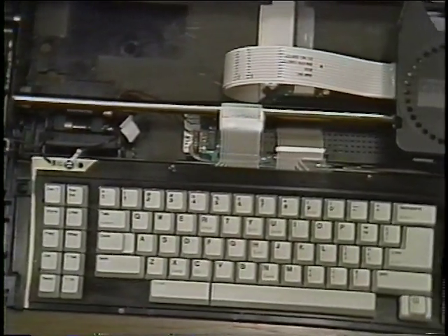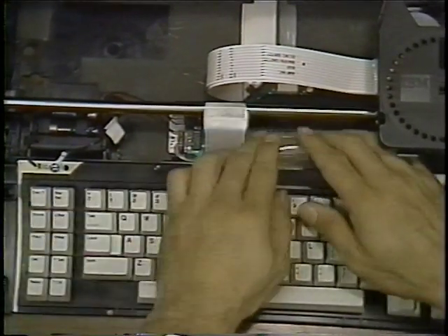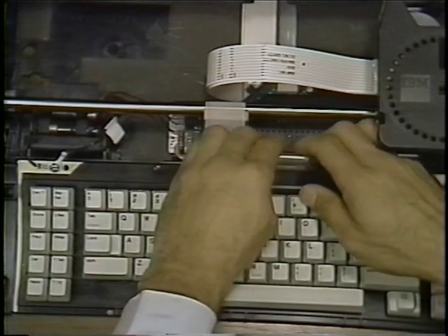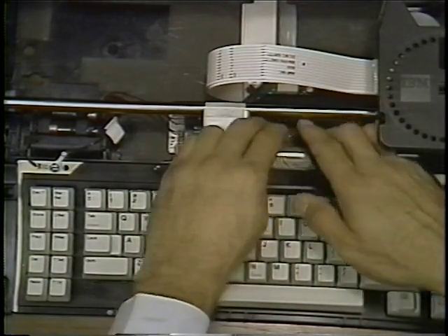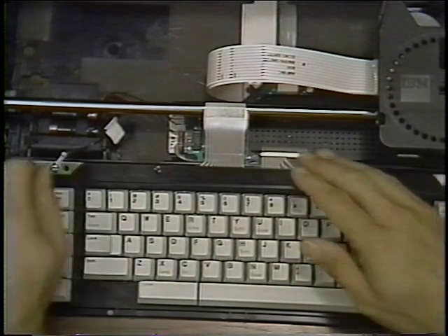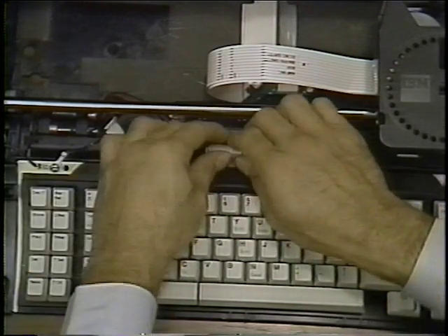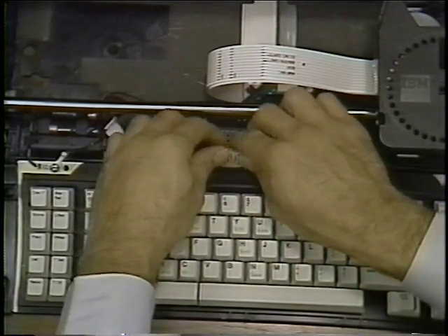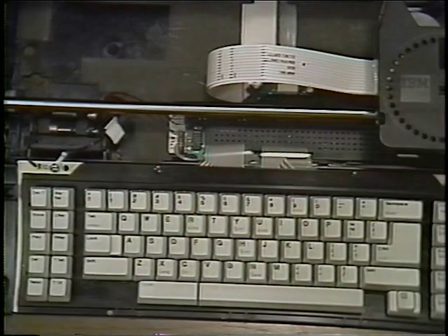Reconnect the sense lines in connector J2F on the function board by pushing the printed circuit membrane into the connector. Be careful not to damage the printed circuit membrane. Next, reconnect the driveline circuit membrane into the J1F connector.